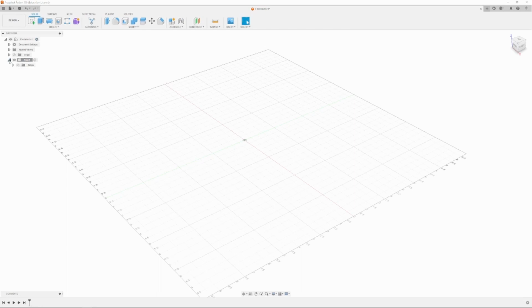If I open up this little thing, it ends up with a copy of everything, kind of like it has in the main view too. As we start creating sketches and 3D bodies, as they're called, it will organize those in here, and it'll add new little folders. So that's how to keep your project organized, in this little file tree. Right now the top is active. It's got this little dot here, so we know that's the active component. So anything we create now is going to be part of the top.